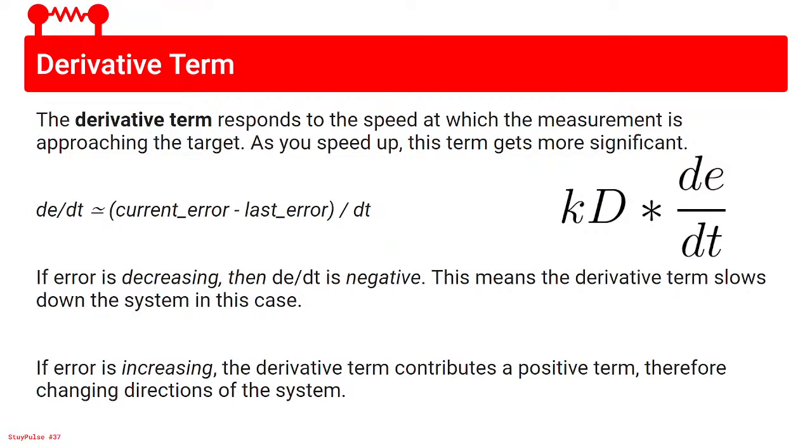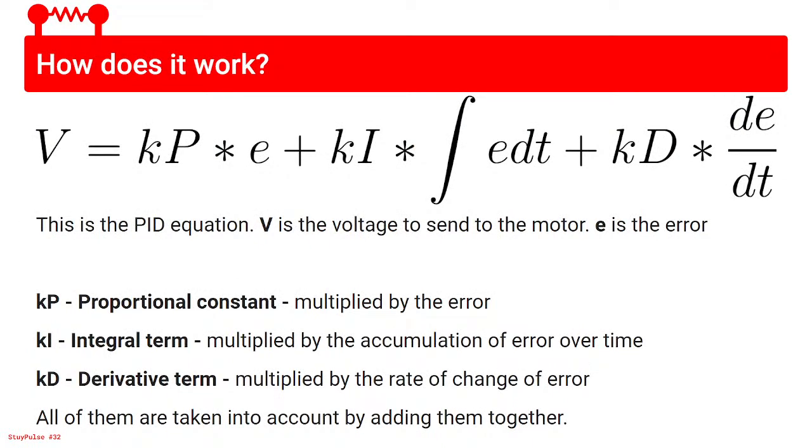And then if the error is... oh yeah, do you have a question? So of course we're finding Kd, Ki manually, but in regards to E, it's being treated as some version of a continuous function. You find a lot of data, define a function that connects the dots. Yeah, that's actually a really good point. I was saying before how this calculus notation, which assumes there's a continuous function for error over time, is not actually what's being implemented. It's just to put it in this formula.